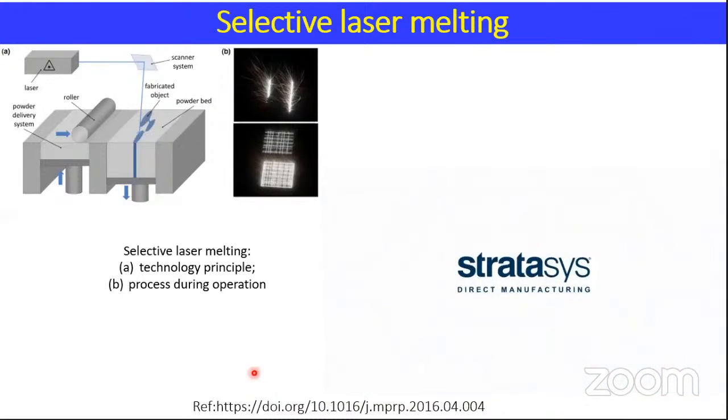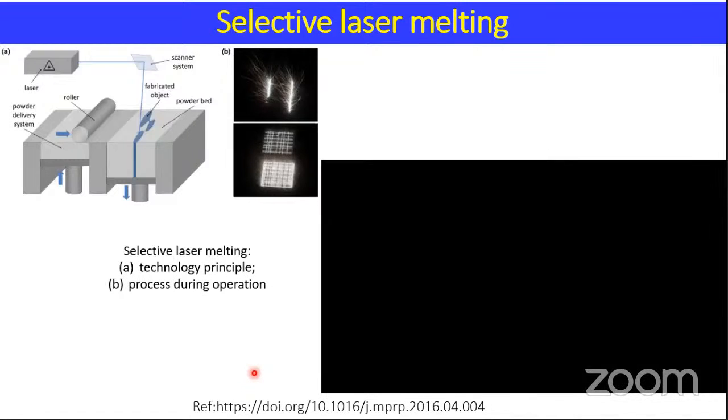All right. So from the video, they also mentioned this technique as the DMLS process, which is nothing but the direct metal laser sintering technique. Typically this is one of the industrially proven and commercialized techniques, which has a lot of potential, especially for aerospace and biomedical, and also recently for automotive applications. People started using this technique because most of the materials we use for these applications can be manufactured easily, right?